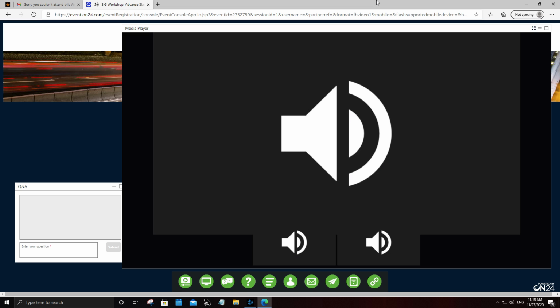There is a question: can we import RAM Structural System to STAAD Foundation? I would ask a reverse question: why do you want to do that? Because RAM Structural System in itself has a RAM Foundation module, which is very robust, and so does RAM Concept.